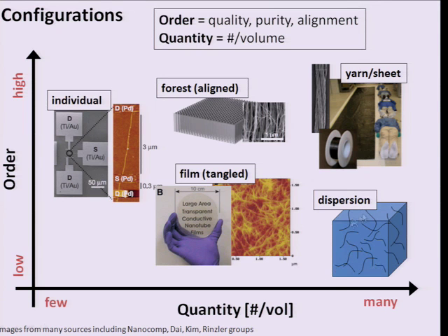And also if we took the dispersions that we made a few lectures ago and mixed them, for example, in a polymer, you would also have a network property. And this was one of the first applications of carbon nanotubes to make plastics have electrical conductivity. Not metal-like conductivity, but conductivity that would be enough for example, electrostatic discharge or electromagnetic shielding. So, these are all examples of different, generally types of networks. And today we'll mainly break down into the idea of what the properties of one of these films would be.